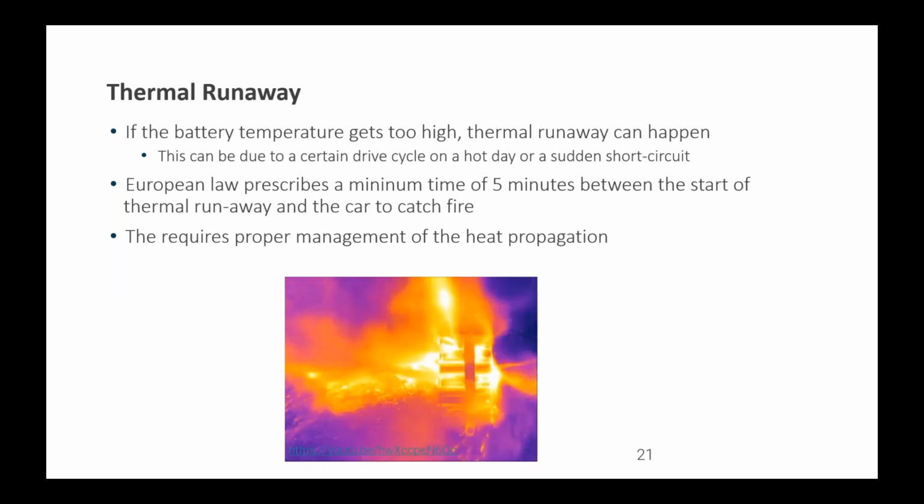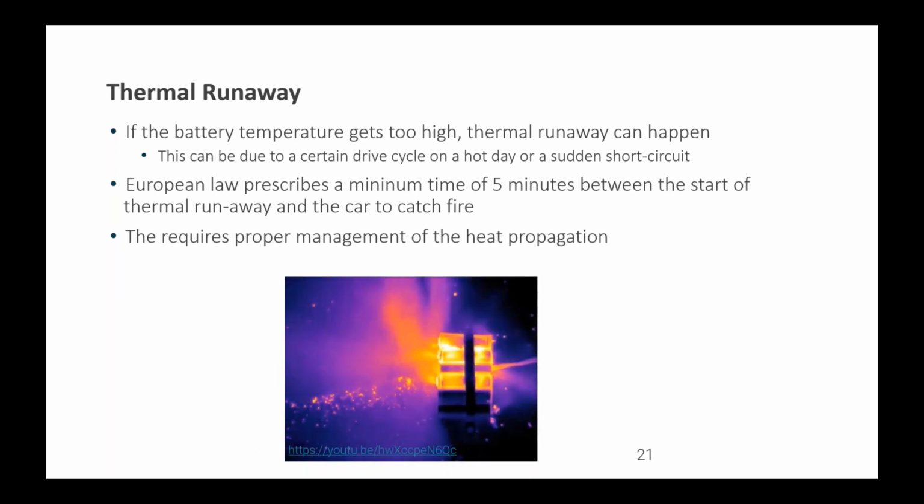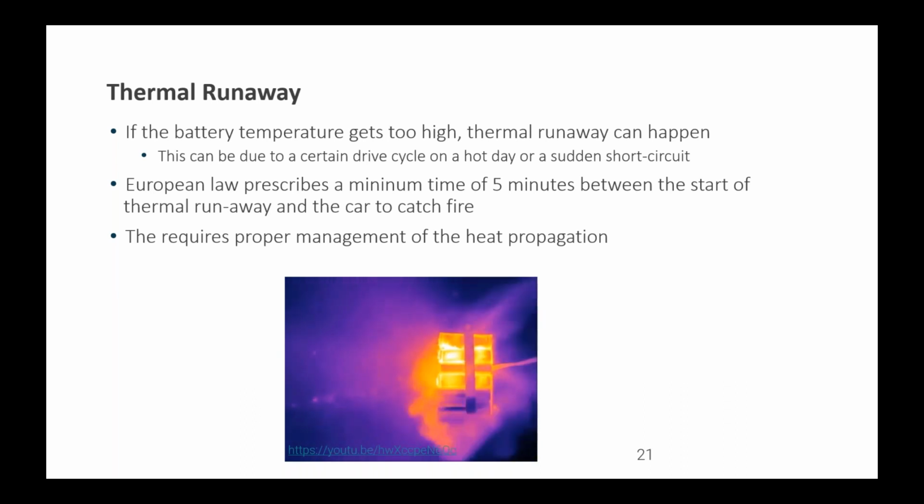So thermal runaway is a very energetic event. When something goes into thermal runaway with the amount of energy density that's packed into these energy management systems, it's hard to keep it from happening ever. And when it does happen, it's probably going to propagate throughout the pack.